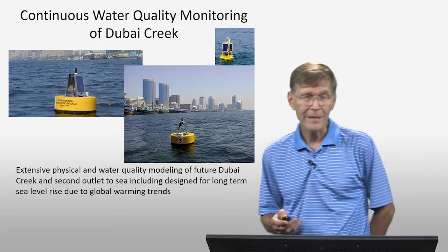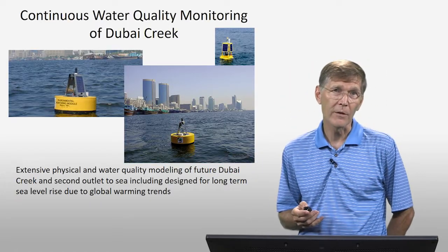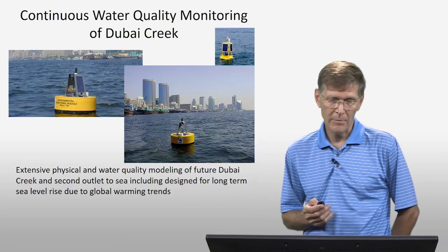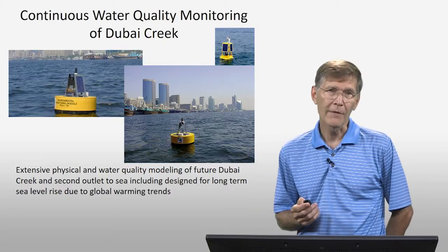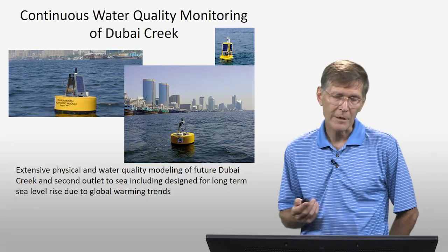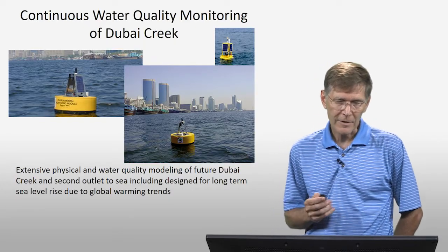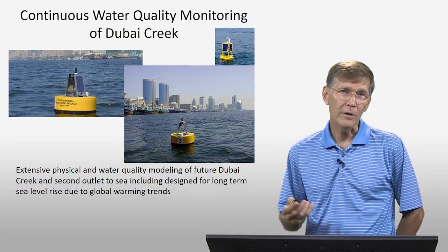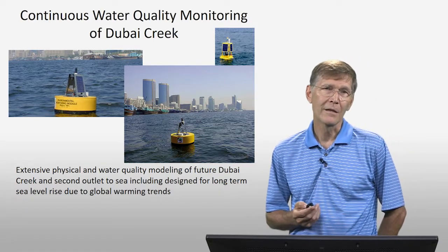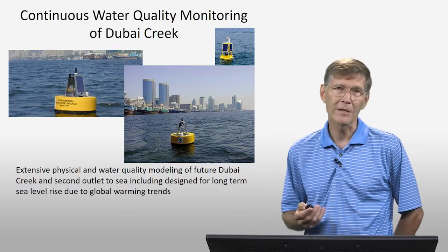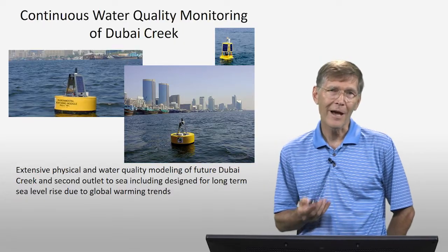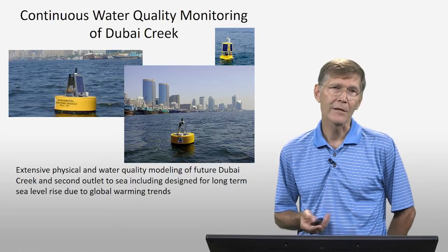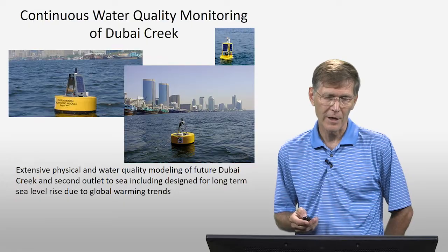We had to study the water quality in the creek, and we set up these buoys with these continuous water quality data monitoring systems. We had a very clever group from Holland, some Dutch guys that were there, and they did these physical models, and they also did these mathematical models to figure out how to design the channels so that you would maximize the flushing. We didn't have a lot of tidal influence there. We had about a half a foot of tidal influence. So you had to use that as best you could and get the flushing to try to clean out the creek.